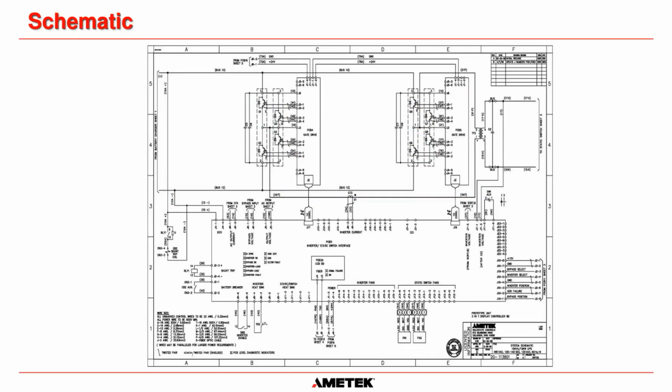And then if we turn Q3 and Q2 on, then we would go down through this IGBT, up through there, and then down back through that IGBT there. And that would give us our positive PWM going in there.